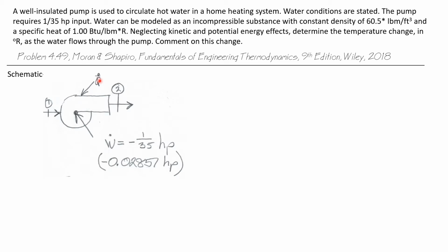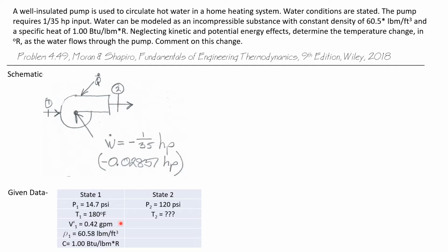There's no heat exchange between the surroundings and the pump, but there is power, of course. This system does not produce work, it consumes work. So the power requirement of the pump is then a negative 1/35 horsepower, and that is a minus 0.02857 horsepower.